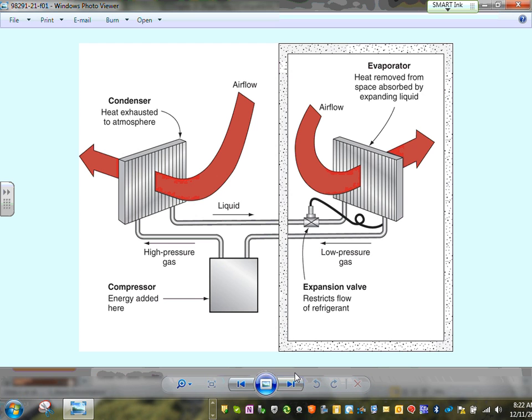To summarize, guys, because we work in coordination with the mechanical engineers, if you don't understand this refrigeration cycle, you'll always be confused. We have an evaporator that picks the heat from the room, and that heat changes the liquid into low pressure gas. Then it goes into the compressor. A compressor will pull it, compress it, and push it back into the condenser. Condenser will blow the heat out, change the high pressure gas into liquid, and it continues in that closed loop circle. Any comments, my friends?